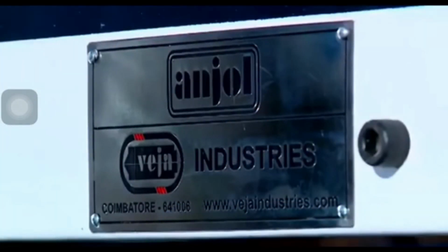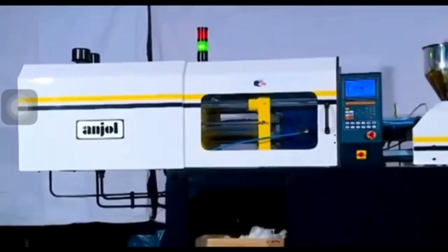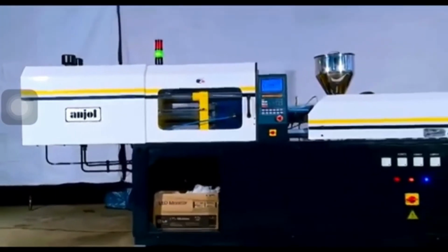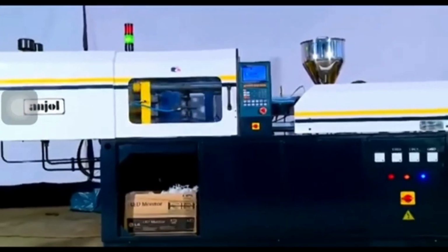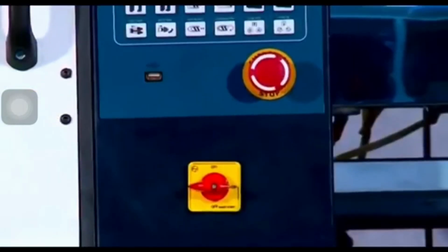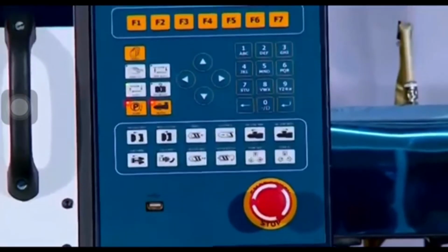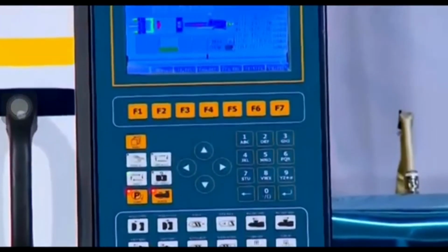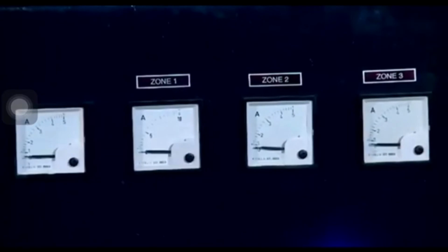The injection molding tool needed to make the molding needs designing and manufacturing. The mold tool is an intricate piece of work which costs manpower, material and many machining hours to make, and represents the larger costs in getting injection molding. Of course, once it is all done, part cost is very low and repeatability very high for hundreds of thousands of moldings.